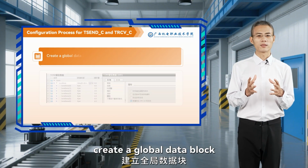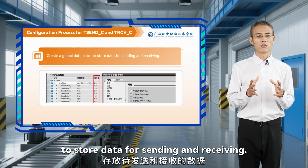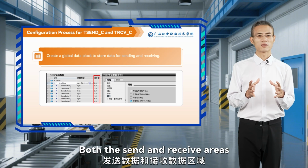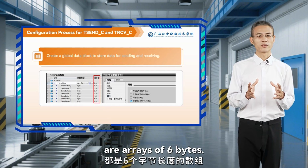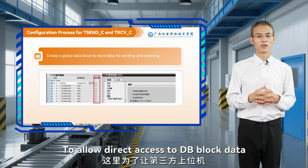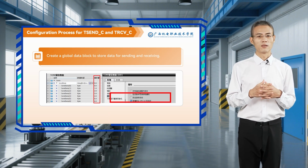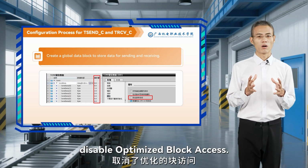Next, create a global data block to store data for sending and receiving. Both the send and receive areas are arrays of 6 bytes. To allow direct access to DB block data by the third-party PC, disable optimized block access.